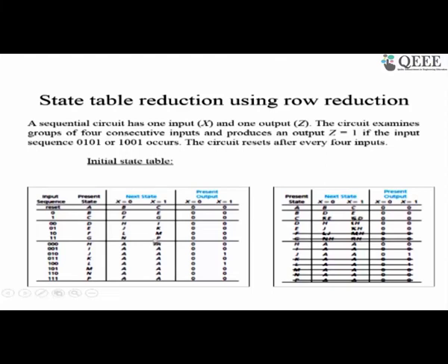So what we have done is we have not bothered about generating new states. Conveniently we have generated a lot of states. Up to now only 3 bits have been obtained, so the output still remains 0. Now the 4th bit comes. Here after getting 3 bits you can be in 8 possible states, from H onwards to P. Now the 4th bit can be 0 or 1.